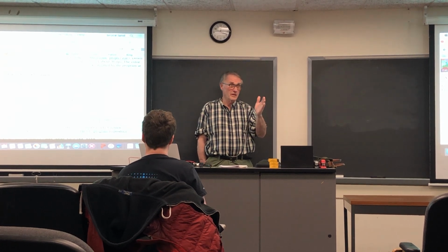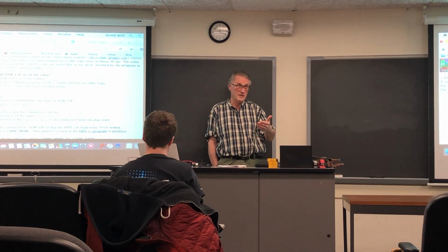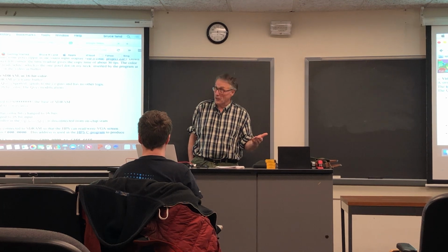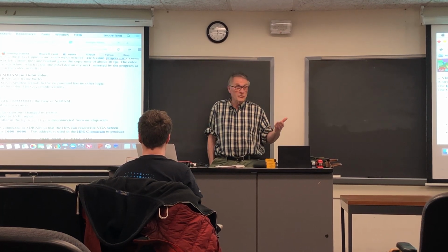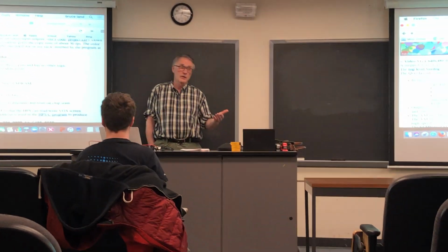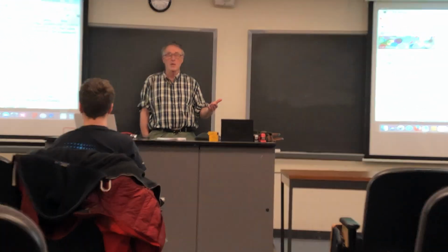Even if you match the constants as well as you can, using 2.75 rather than 2.66, since 2.66 is a continuing fraction in binary and the truncation is done differently in MATLAB and in fixed point, you'll get a better result with 2.75.